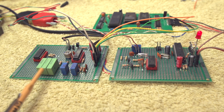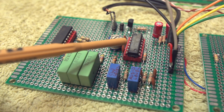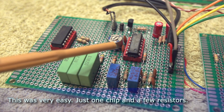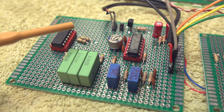It's all I had lying around. We've also populated this area here. This is new. Let's have a closer look at that. Yeah, so here we are. We managed to reverse engineer the switching circuit, the audio switching, or the audio routing if you like, from the original card. Once you know the pinouts of the 4066, it's not difficult at all.